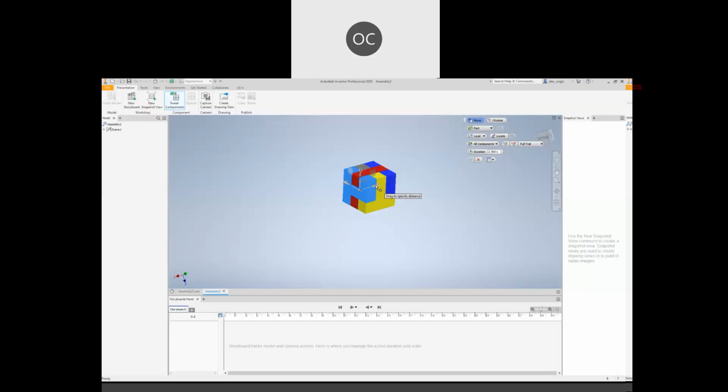That means click, drag. You see? This one we know is the Z-axis, a negative value. If you want a constant distance between your parts, then you key in negative 20 over here. The distance will be calculated from the datum to 20 on the Z-axis. Then I click OK.